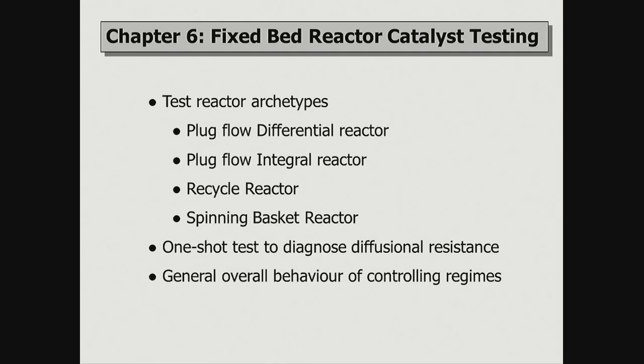Recycle reactor you're familiar with. A little spinning basket reactor you might not be. And I'm just setting one of those up to do alkylations up in the lab upstairs. And it literally is a pot with a basket and an agitator. So imagine your setup that you've just seen blow up with its agitator, but now picture between the two blades, picture a basket which has got a catalyst in it. Okay? So it's doing mixing, so it's helping to get the effects of energy that might be released or energy that's being sucked in. It's actually mixing, but the catalyst remains static, but the contents are moving through the catalyst. The posh version of a spinning basket reactor is indeed called a Berty reactor. That sometimes is easy to remember. So we'll have a look at that.